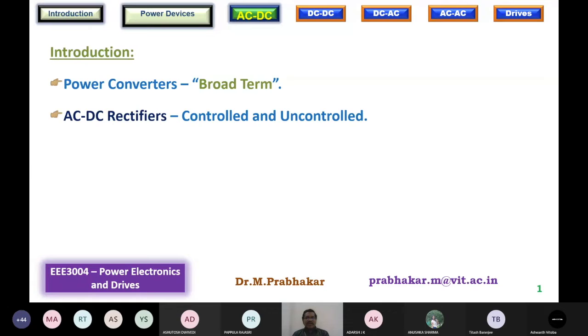The transformer peak inverse rating will be affecting, and the transformer leakage inductance will affect the device, which will be ringing. More importantly, nowadays the bridge comes in the form of a brick, an intelligent power module, IPM, or smart power module, SPM. Therefore, only bridge configurations are going to be considered. It goes without saying that whatever power converter we deal with will be only the bridge configuration.